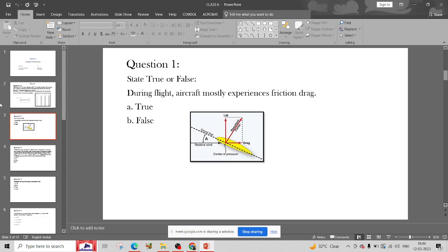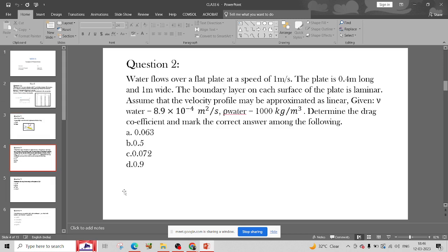It will increase the friction drag and it will decrease the pressure drag. Thus, an object must be tapered enough to reduce the size of the wake, but it must also be short enough so that the accompanying friction drag doesn't offset the lower pressure drag. As friction drag is also less, the pressure drag is also less. So we need to minimize the area.